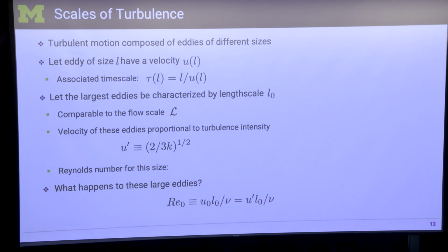So you do this, and you get a Reynolds number. Now you see that it's a Reynolds number that depends on the length scale and the velocity. Which means that if I change the length scale and the velocity, the Reynolds number is going to change. So even within the same flow, for different eddies, I might have different Reynolds numbers. We used to think of Reynolds number as something for a pipe: what's the Reynolds number of this pipe? You look at the velocity of the inflow, the diameter of the pipe, the viscosity, and that's your Reynolds number. Here it's not like that. This Reynolds number itself is a time-varying, spatially varying quantity. So there are many different Reynolds numbers that you can define in a given turbulent flow, okay? This is something to keep in mind. It's also a bit confusing.